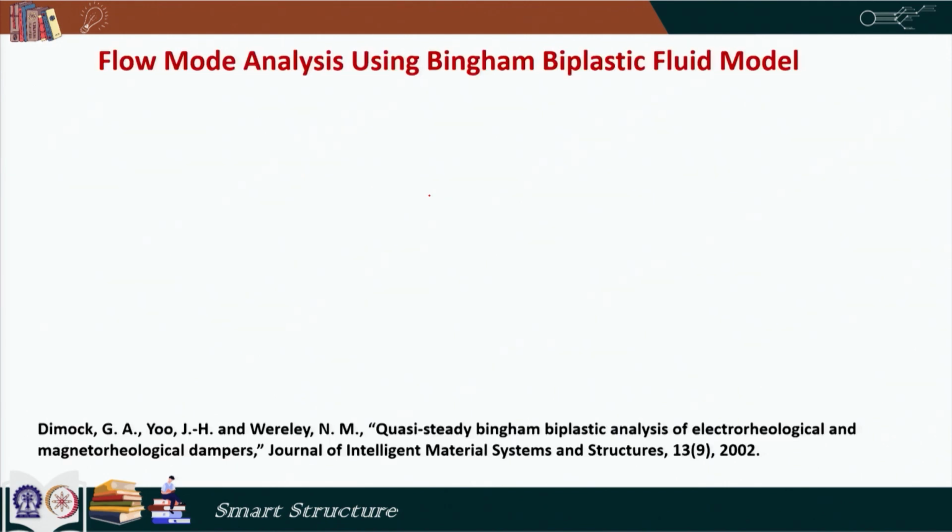Now, this brings us to the end of this flow analysis using the Herschel-Bulkley model. Next, we will do a similar analysis using the Bingham biplastic model. The Bingham biplastic model is a modified version of the Bingham plastic model to incorporate shear thinning or shear thickening behavior, and a little more detail about the model can be read in the paper that is referred here.